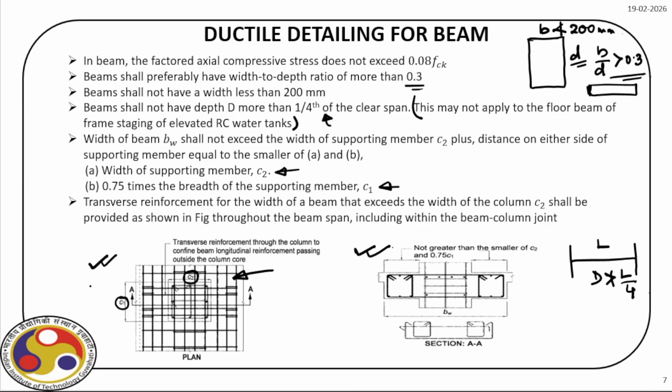Okay. Now, just recall, if we have a frame structure like this one, earlier we discussed, say there is some loading here, we discussed the design of beam at this section, then design of column, then we designed the column at these sections. But now we focus at the corner, at the junction where we have the load transfer between the beam and column, because during this large deformation, it is this section which is critical and that will efficiently transfer, and if the situation arises, redistribute the moment among the joints.